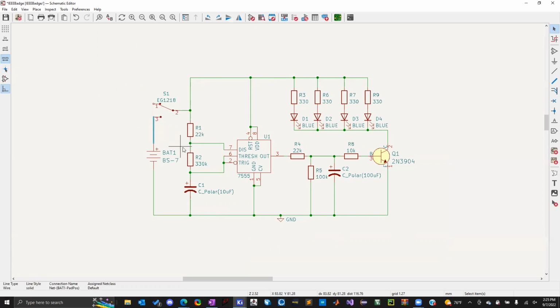If it's not the correct pins, the 1, 2, 3, you can flip the component by using these here. This is by the x-axis, this is by the y-axis. It really doesn't matter, whichever side is connected.